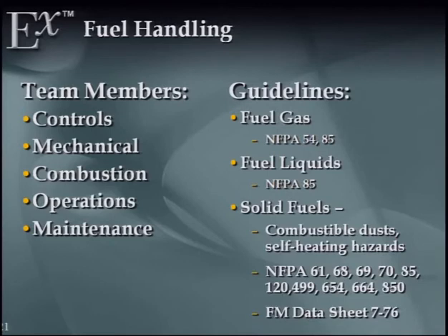Then solid fuels, which is quite a wide range. There are combustible dust hazards. The list of NFPA standards here that I've included is pretty broad. There's work right now to come up with a more comprehensive NFPA standard to cover dust handling. But I still have questions about how well that's going to apply to coal handling systems. There's an FM data sheet out there.